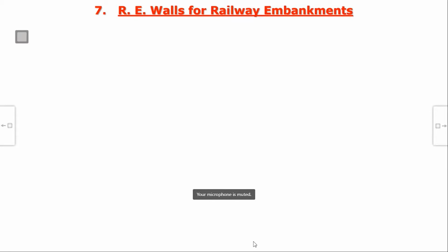The whole world, including your space shuttles and big ships and cargo ships, they are made with welding. We also in railway nowadays, you will see most of our girders are welded. What it requires is proper quality control in welding and a proper system so that we get a proper product. Similarly, in PSC girder also, as compared to heavy RCC, in some cases, not all, it may collapse in a catastrophe. Does that mean that we don't use PSC structure? We are using it. So the need is to do proper design and proper work rather than being afraid of this. Maybe we start in a small way.